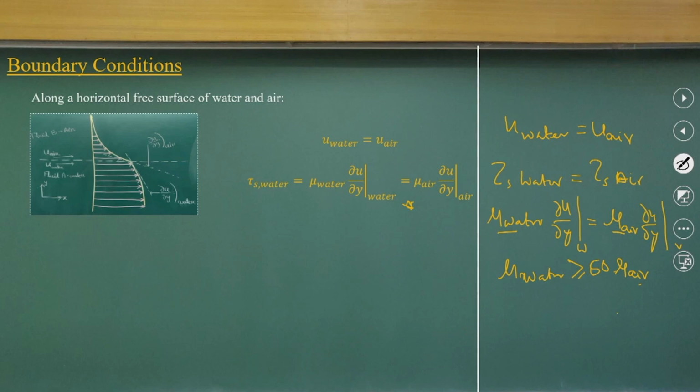That is the reason we consider it, and you can always draw the velocities, which is very interesting here. If there is an interface and I draw the velocity distribution, in air I will have a very fast gradient to support these boundary conditions, but in water we will have less, because it is 50 times lesser. So, I will have a velocity distribution like this at the interface.